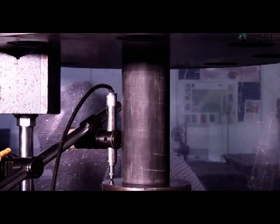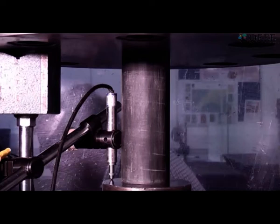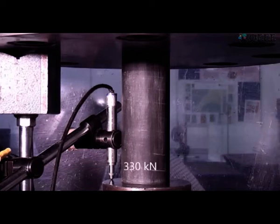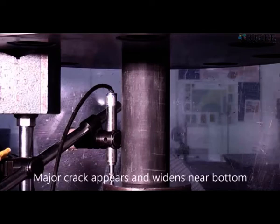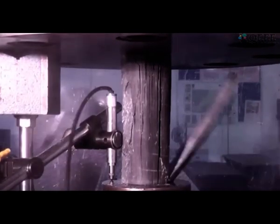You see, this is the compression test on a brittle material. It's around a 1 minute video. You see how it fails. You see the load is increasing slowly. You increase the load, but you don't see any sign of failure. And suddenly, when the load reaches a certain value, it breaks. All of a sudden, it fails. Means in this case, the failure is very sudden. Before it fails, it's very difficult to foresee the failure. It hardly gives any sign before it fails.